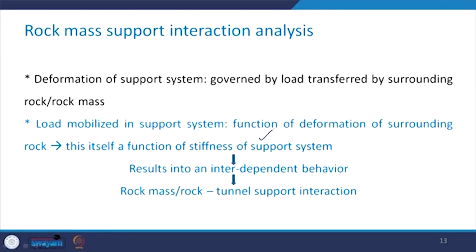This is a function of deformation of the surrounding rock, and this deformation of the surrounding rock itself is a function of the stiffness of the support system. So, you should be able to visualize that this whole phenomenon results in an interdependent behavior, and therefore, this is called rock mass or rock tunnel support interaction.